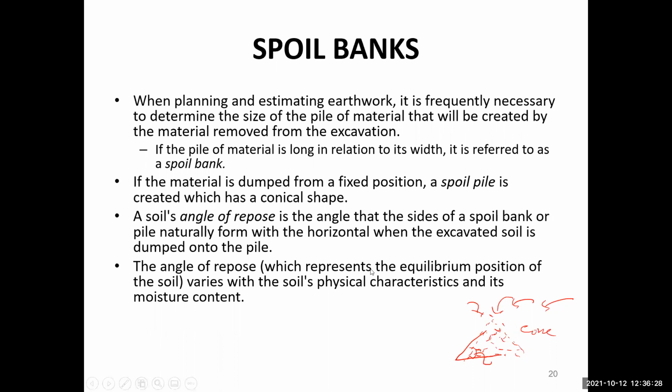The angle of repose, which represents the equilibrium position of the soil, varies with the soil's physical characteristics and its moisture content. Normally, if there is a clay, the angle of repose will be high, especially when the clay has some moisture in it. If it is sand, the angle of repose will be less because sand is quite loose, especially when it is dry. So the angle of repose for sand will be less, and for clay it will be high.